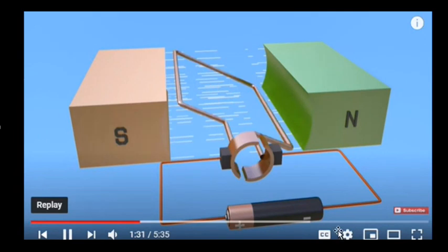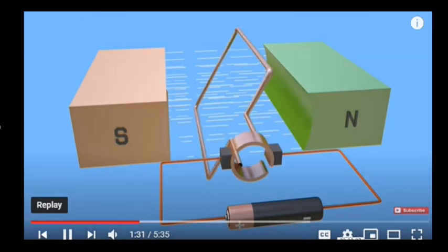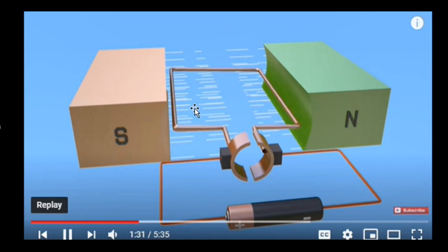So what's happening? Now when it changes direction, this left side should come on the right side and the right will come on the left side, but the direction of current from the supply will remain the same due to the commutator. So this was the function of the commutator, that it changed the direction of current in the coil. Meaning if this side is upward, when this side comes to this position, the direction of current will be changed, it will be downward. Who is responsible? This commutator.